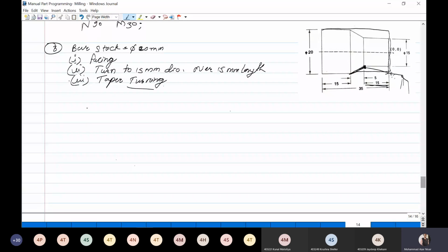So first, again the same lines. I will write it fast. M05, G90, G71, G18, G94, G55, or 54 to 59. You can take the G code for saving this workpiece 0.